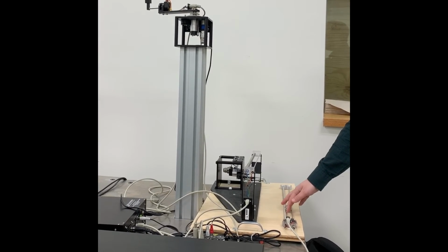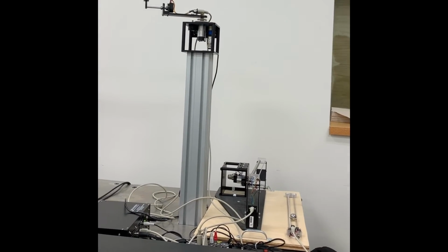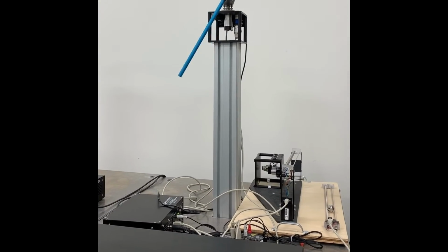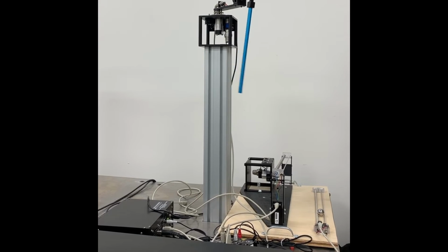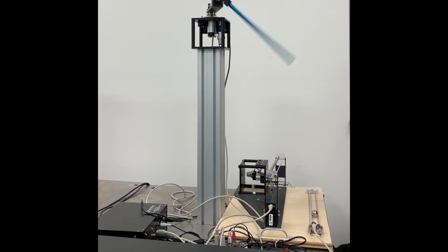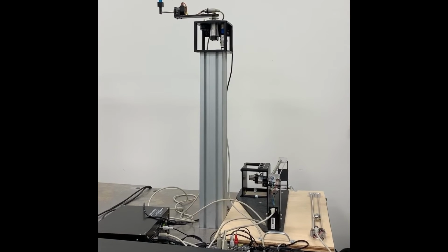For the swing up to work correctly, the Q2 term had to be reset so that the bottom of the swing was set to 0. Similarly to the stage controller, this required the position to be normalized, which again required the use of arctan2. We could have alternatively controlled the swing up stage by using a Hamiltonian energy approach.